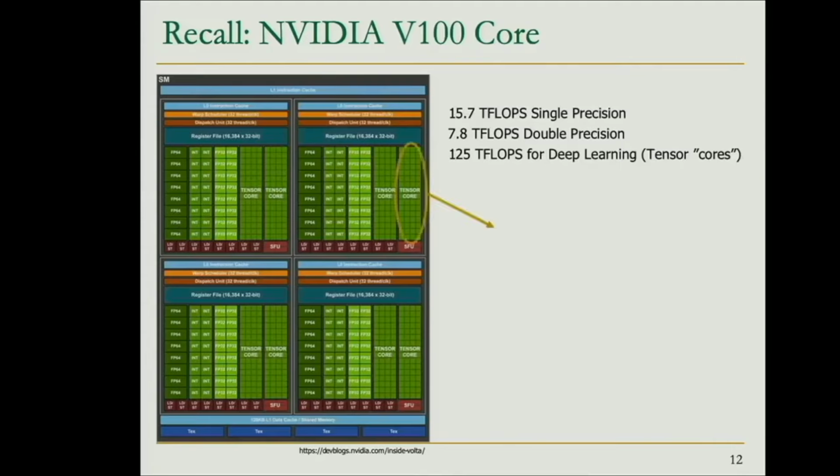What exactly do these tensor cores mean? Well, it's something like this. For each of these tensor cores, we are going to be able to do this computation. Observe that we have 2 input values, we multiply them, and then we accumulate the partial result with more products coming from other tensor cores. As you can see, this is able to do a sort of mixed precision. We are not working with single precision or double precision floating point operands, but with half precision. This is 16 bits to represent the floating point number.